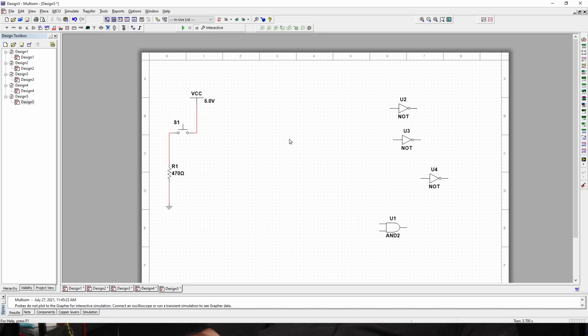Let's just confirm that. So in Multisim we can get meters here. Here's the menu of different devices that we could use, and the very top one here, if you just mouse over it and stay there, it's going to show you what things are. So I'm just going to mouse over the multimeter, click on it, and now I'm just moving the mouse, not holding any buttons. I can place this multimeter anywhere I want. So let's say I'm going to put it right here. Okay, and now we're just confirming that.